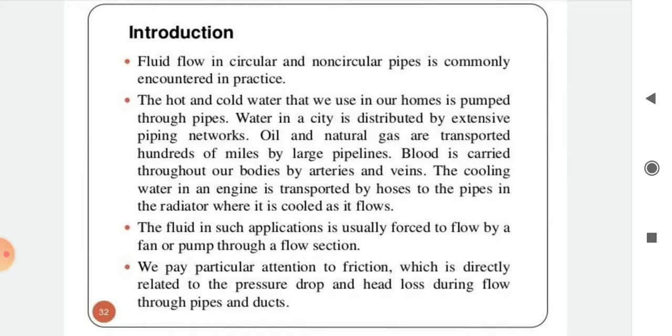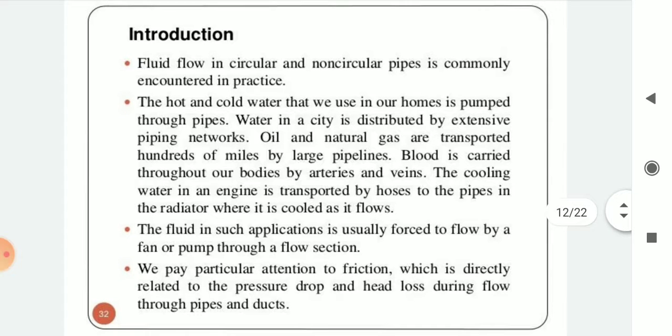The cooling water in an engine is transported by hoses to the pipes in the radiator where it is cooled as it flows. The fluid in such applications is usually forced to flow by a fan or pump through a flow section. We pay particular attention to friction, which is directly related to the pressure drop and head loss during flow through pipes and ducts.